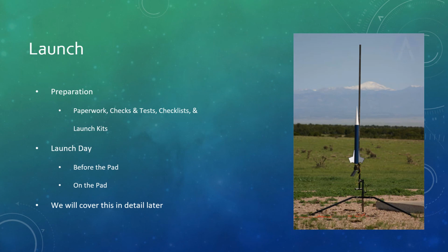And if you have an electronics bay, this is when you would activate your deployment electronics. You want to do it at the very end, because if there is any malfunction, or if you have to adjust your rocket, you don't want to have to take your rocket off the rail with your electronics on, because it might detect the change in orientation as reaching apogee and then set off the charges while you're taking it off. So no bueno.